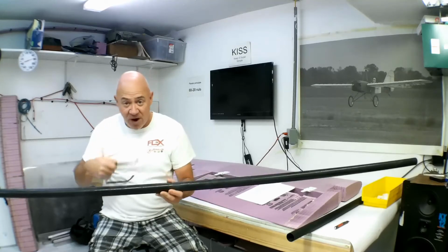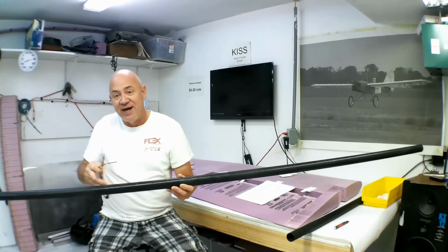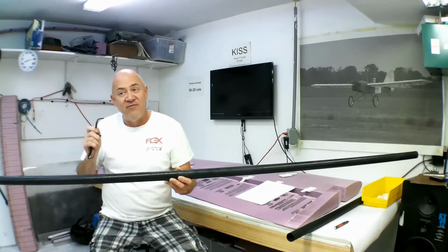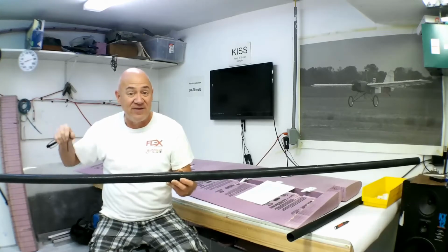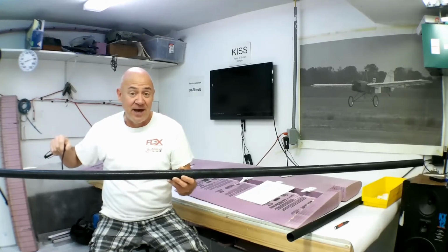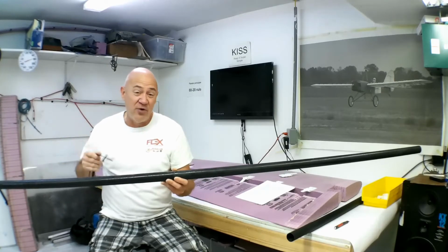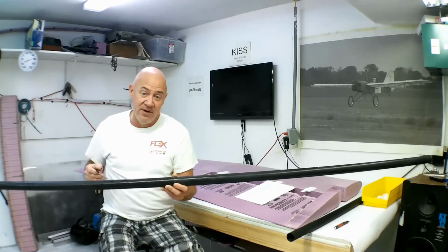But if you do this right, by going out that 50 to 60% of the wing, it's the same as putting the sandbags all over the wing that you see full-scale airplanes do. Keep in mind, full-scale airplanes, when they put those sandbags in, are also testing the strength of the skin, to make sure it can't collapse. All we're worried about on an RC plane is a spar, because I doubt any of you are going to build so light that your skin can collapse from aerodynamic forces.